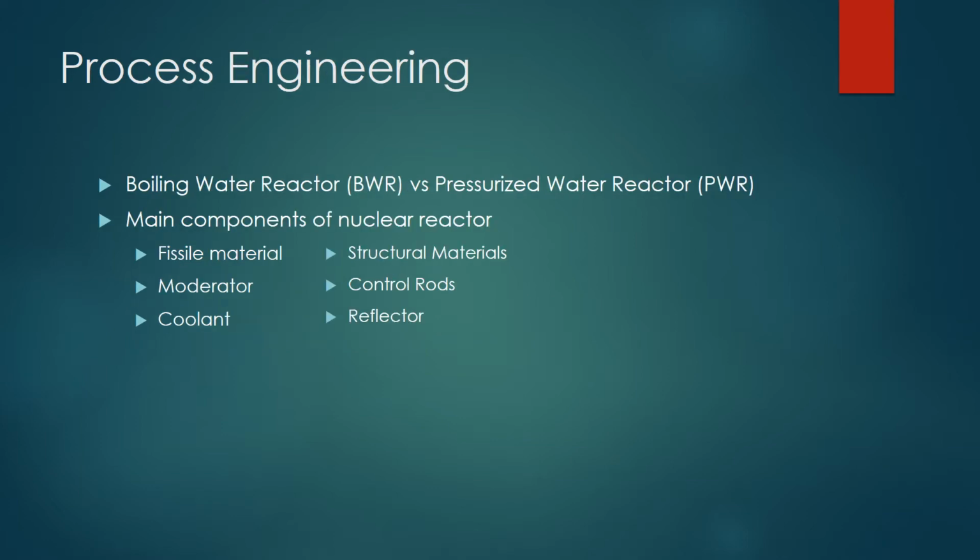Currently, all fission reactors are boiling water reactors and pressurized water reactors. So we chose the boiling water reactor over the pressurized water reactor because water can be used for a moderator, coolant, and as a reflector. Additionally, the boiling water reactor can operate at lower temperatures and pressures, involves fewer heat exchangers, and is just an overall simpler system.